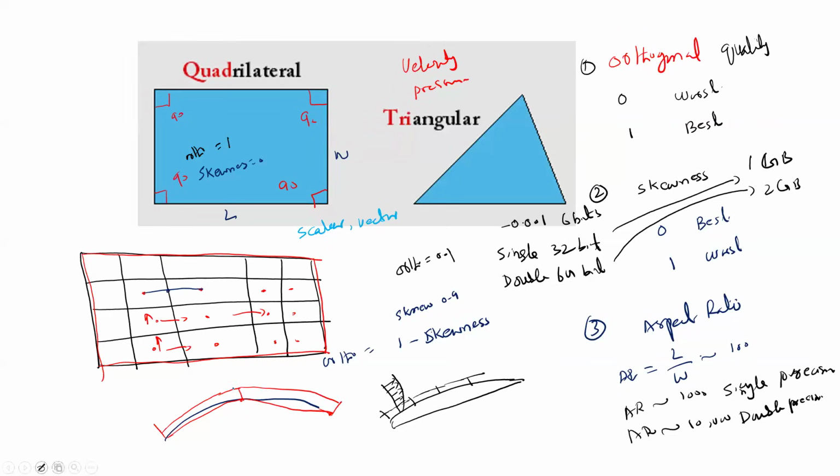Now imagine that we have to interpolate data on this cell's face over here. So this is one point here. Now definitely the node will be placed over here, that is the center of the cell, not the center of the geometry with respect to the boundary over here. So one node is over here, second node is over here. Okay. So now if you join these two nodes, what will happen? You will be getting a line that is like this way.